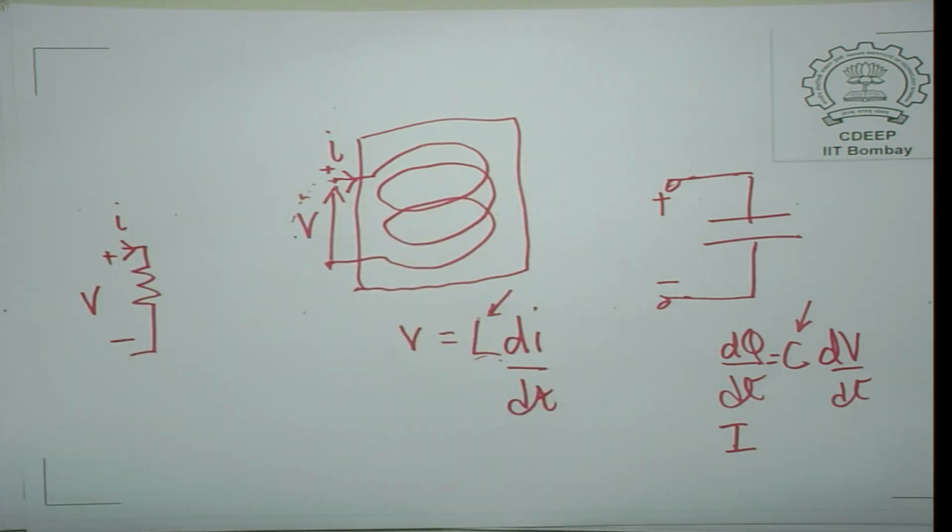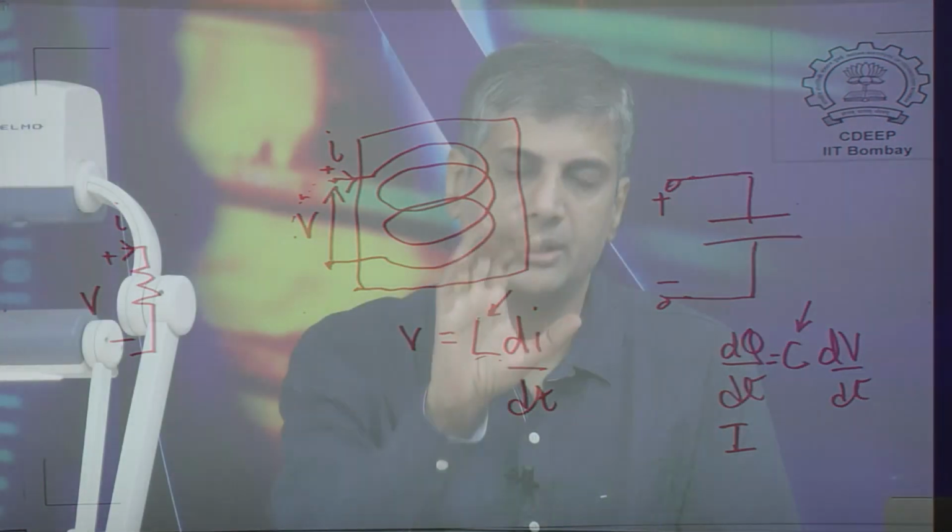So, when you are applying Kirchhoff's law, you should be aware of the signs of voltages and currents. Of course, we did mention mutual inductances. In mutual inductances, you can have negative signs for mutual inductance. In fact, let me just recapitulate.